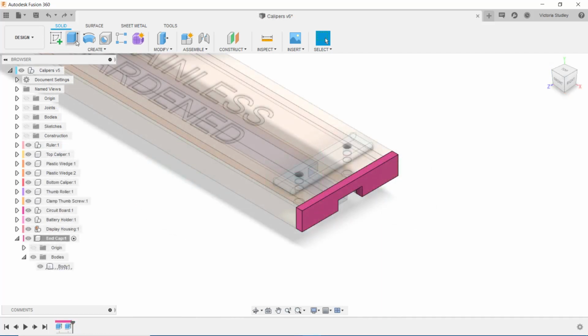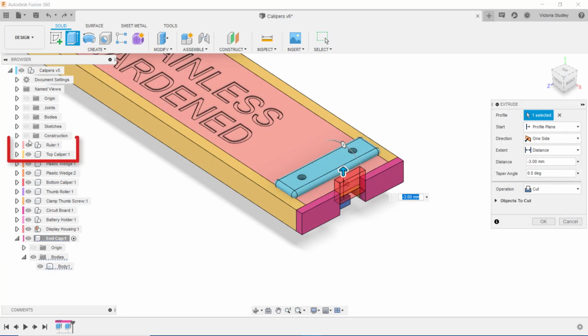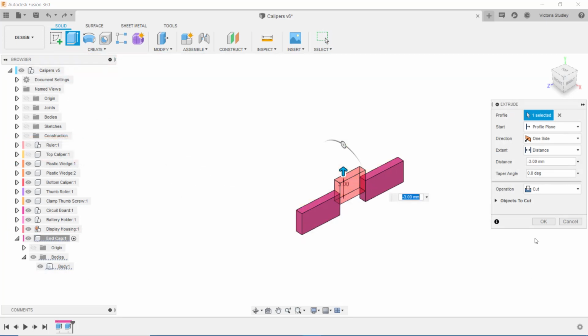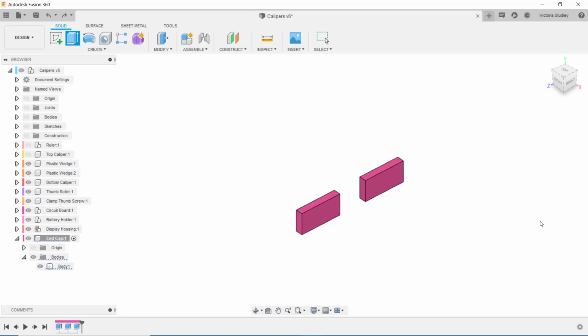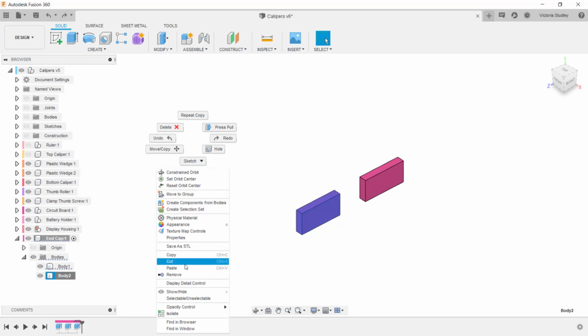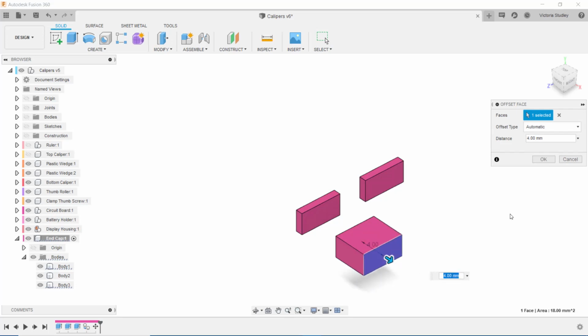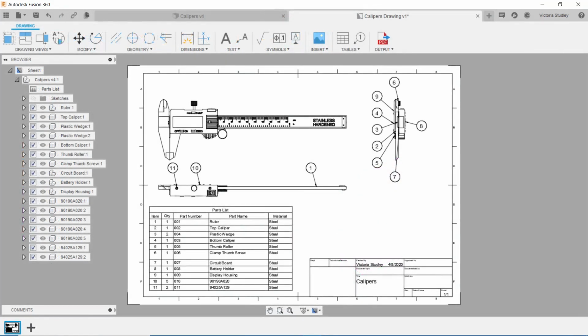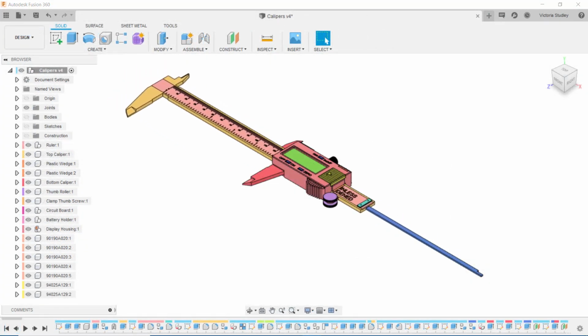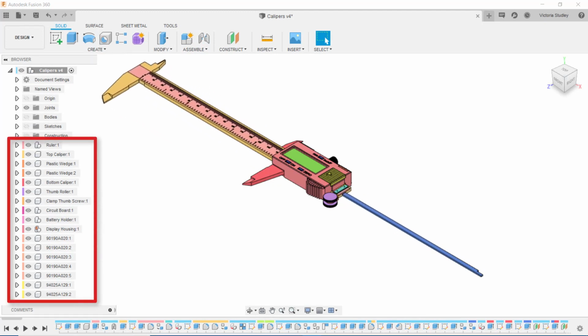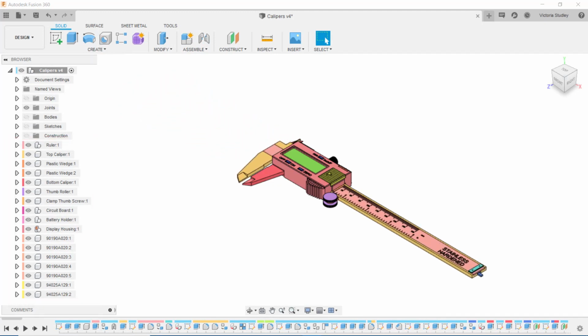There are a few things that you should consider when creating bodies. Before you modify a body, make sure you activate its component first. Consider hiding other components when you modify a body to avoid creating unnecessary relationships between bodies across different components. If you copy and paste a body, each copy remains independent. Changes you make to one body will not affect the other. Bodies do not display in drawings or in a bill of materials. And if your design requires motion between components, it's best to create components first, then create bodies within their respective components from the start.